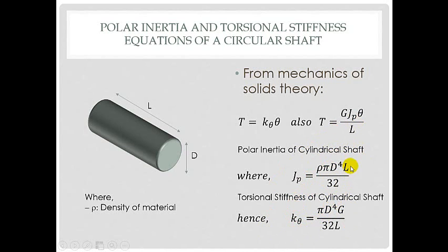When we do some of the modeling and when you see some of the results, you'll understand why it's important to make some changes in your design phase, to accommodate certain torsional issues that can come up. So the best way that you can affect your torsional inertia or your torsional stiffness is by changing your diameter.